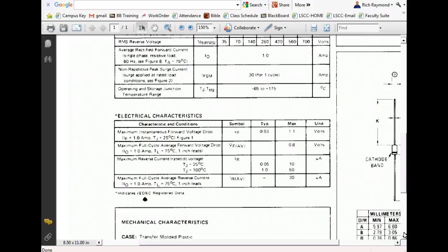Yeah, it reduces oxidation. So you don't want to file those leads off because you'll get down to the copper, and then the copper oxidizes and gets into your solder joints. Plus, they use a tin coating, or sometimes nickel. Solder also adheres to those metals better than it does copper. So it's actually easier to solder to tin.